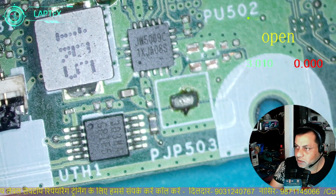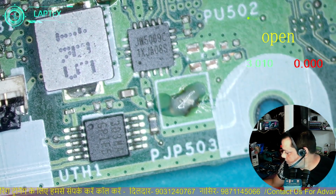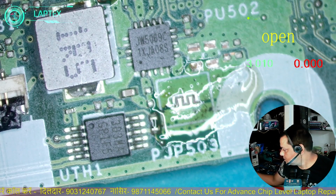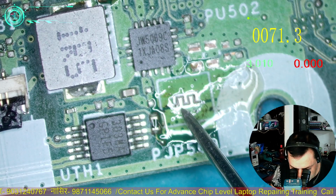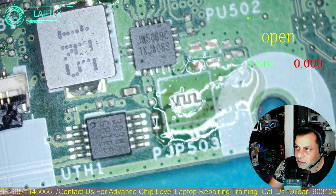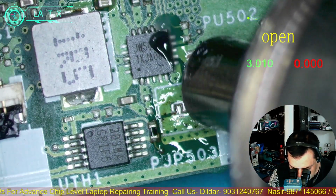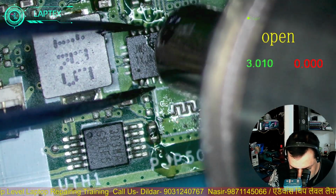So do one thing, don't remove anything, you just clean up this jumper point, clean up like this, and find out whether this area is short or not. This side shorting is removed, inside there is a shorting, it means this is the faulty IC. Now remove it. I think this is a 5 volt regulator, JW.